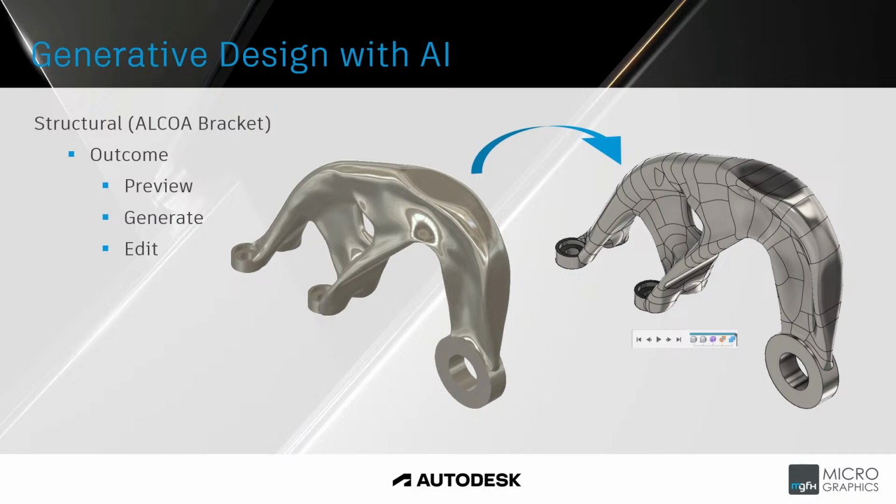The timeline is showing us that we have some solid geometry, which was the initial starting geometry that we set up. That would be those green pieces. And then the shape is actually created using Sculpt within Fusion. So that's the freeform shapes, which means that we can actually go in and edit and modify this if required. If there's certain areas that we're not happy with, we can clean them up and edit the shape, modify it, and then run a stress analysis to verify our results.